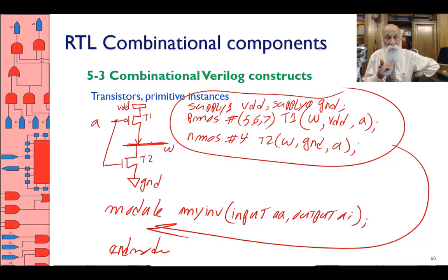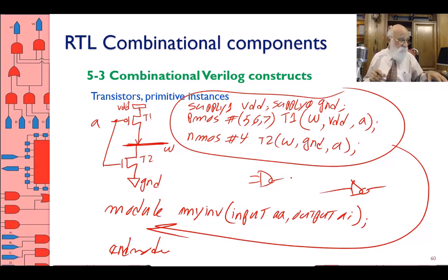That's why, because you always put NMOS on the ground side and PMOS on the supply side, all the complex gate structures you develop are all inverted. Like this one is a simple inverter. Okay, if you put two transistors in series and two in parallel on the top, then that becomes a NAND gate, and that is a NAND gate. So again, it is inverted. Okay, with CMOS structures, you cannot build AND gates and OR gates.